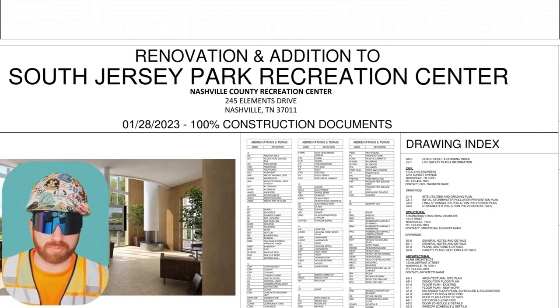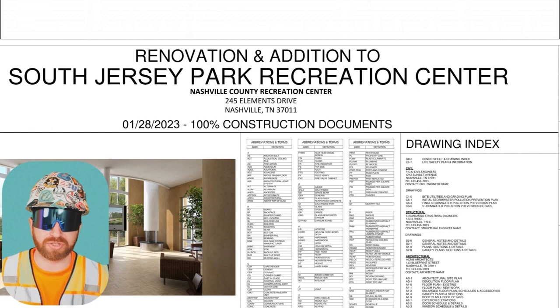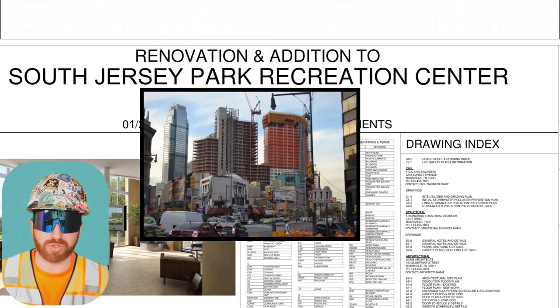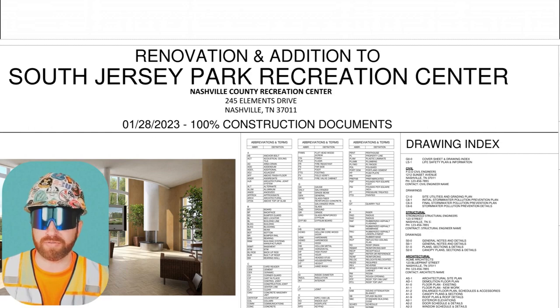This would be extremely important as a general contractor or a construction manager to help understand the logistics of building this project. For instance, is there a lot of space on the existing plot for laydown of materials? Is this new building going to be sandwiched in between two other buildings so there's no space for parking or anything else? Is there a highway close by for deliveries? These are just things that would run through my head as I'm reading through this. I'd also always suggest completing a site visit so that you can physically see everything that's involved in addition to reading these drawing plans.